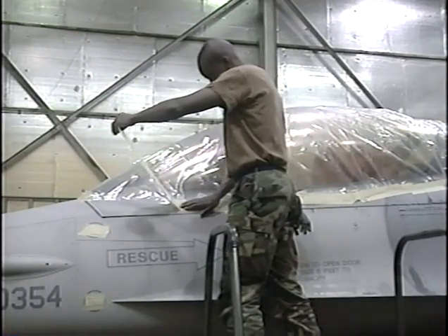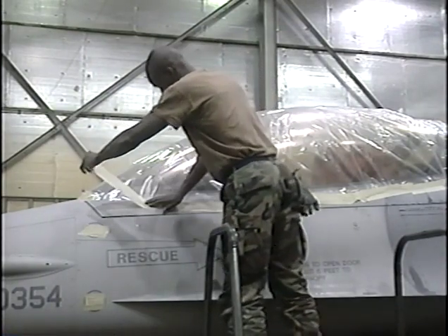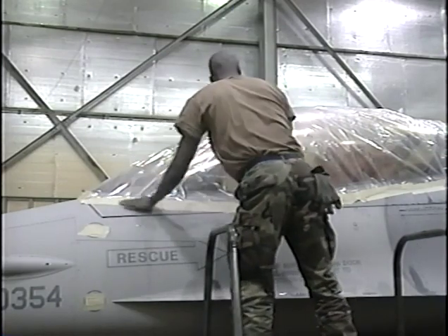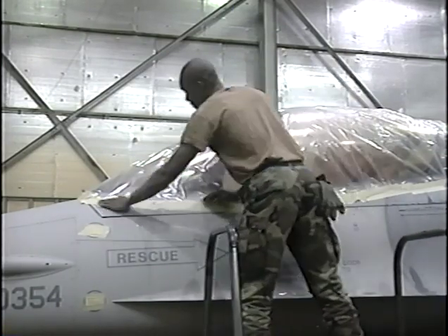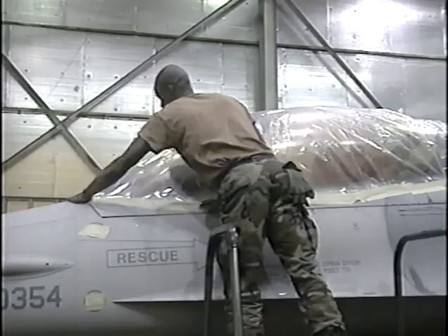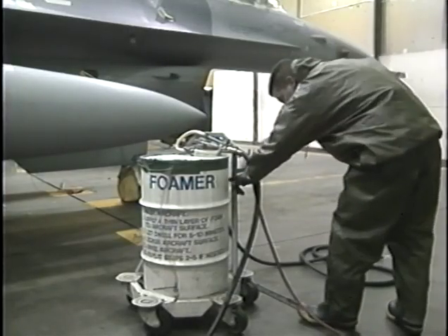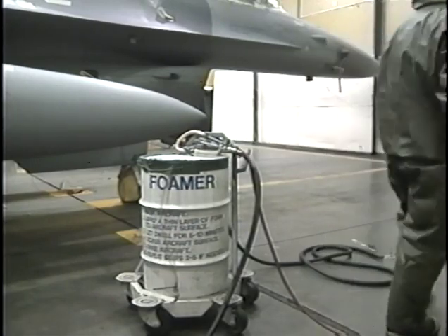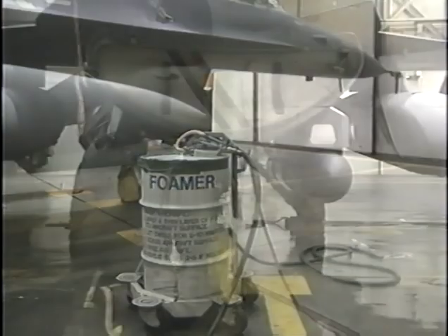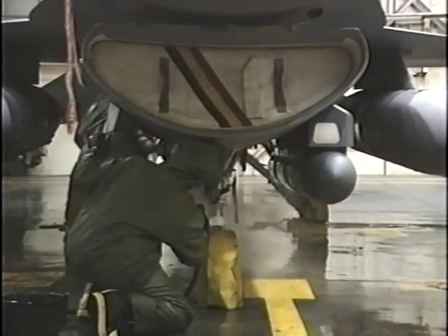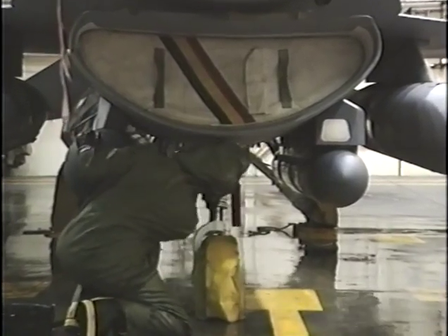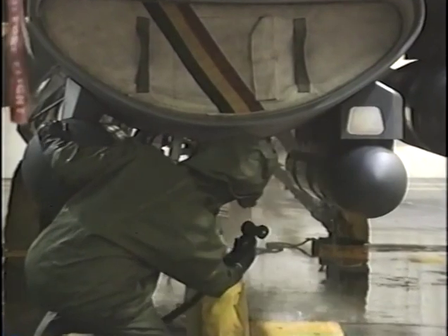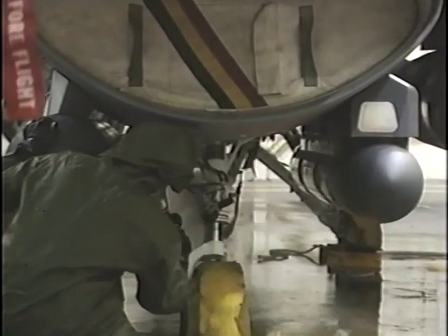Before starting the aircraft wash, you must ensure all areas that shouldn't be exposed to cleaners and solvents are covered. Check the applicable aircraft tech data for these requirements. Ensure the correct aircraft cleaners are used and the dispenser is set at the proper mixture ratio. Be careful not to direct the aircraft cleaners into areas containing exposed connectors or seal-type bearings. Also, avoid spraying it into areas where there isn't adequate drainage.